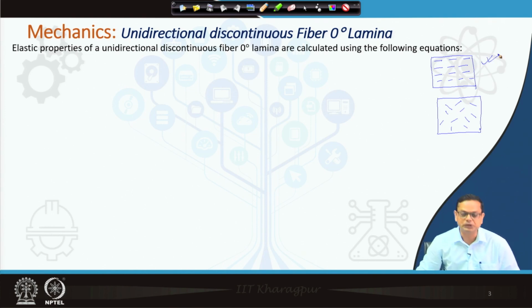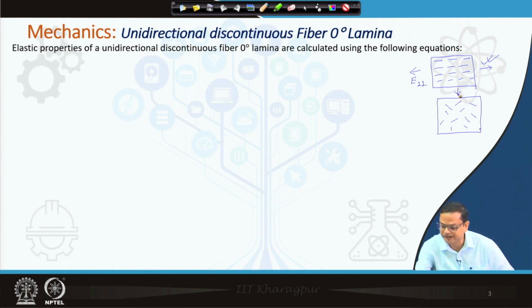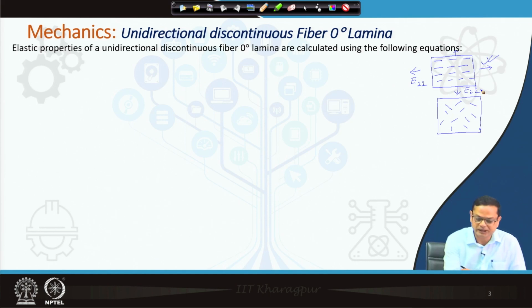Now, if we apply load in this direction and try to measure the modulus, we call it E11. Similarly, if we apply load in the transverse direction like this, in that case we get the value of E22. Now, based on a set of equations given by Halpin and Tsai,